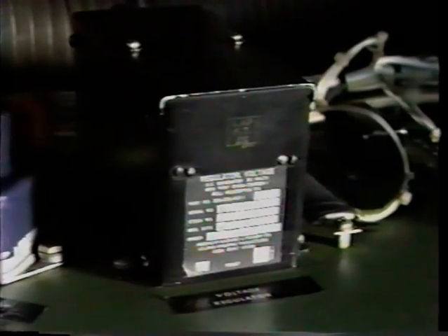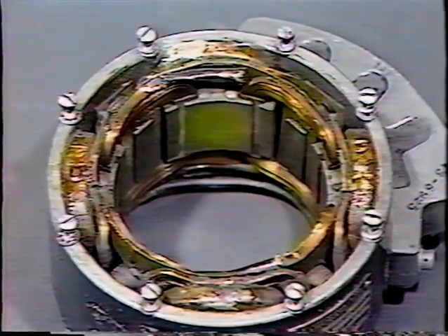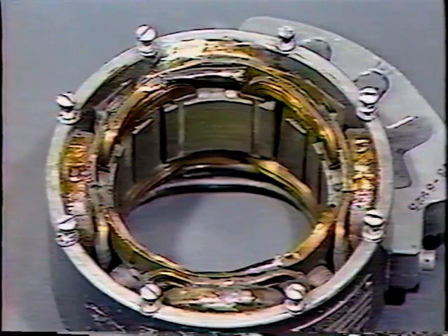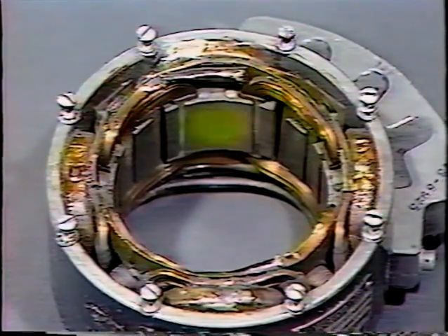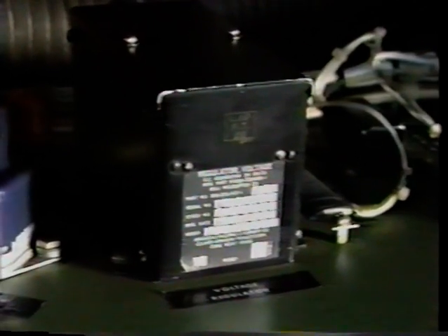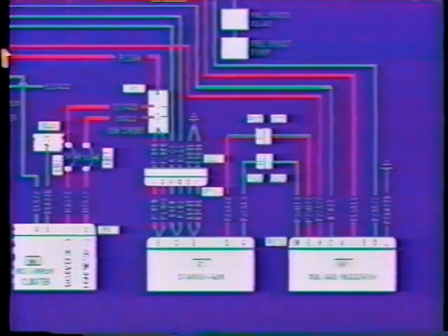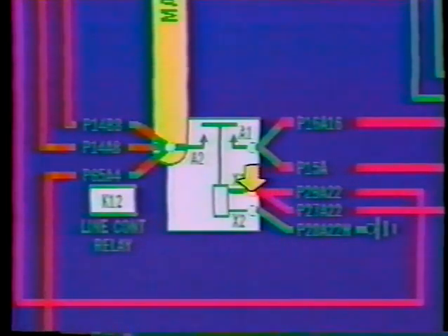The voltage regulator, in its operation, varies the resistance within the shunt field windings through the voltage regulator's pin G to the generator's pin D. This increasing and decreasing of generator shunt field windings by the voltage regulator regulates the output of the generator. With this most important task completed, the voltage regulator will allow controlling power to leave the regulator via pin H and be transmitted to the line control relay's X1.